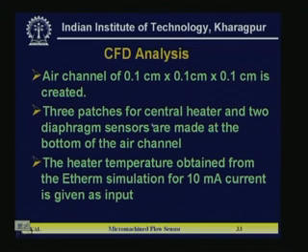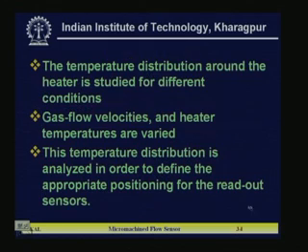3 patches for the central heater and 2 diaphragm sensors are made at the bottom of the air channel. The heater temperature obtained from the E-therm simulation for 10 milliampere current is given as the input for CFD. The temperature distribution around the heater is studied for different conditions.